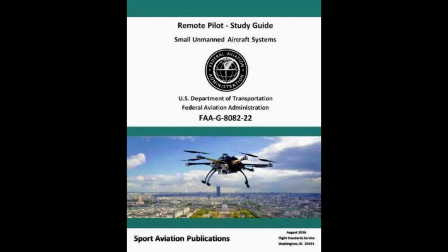2. Weight changes during flight also have a direct effect on aircraft performance. Fuel burn is the most common weight change that takes place during flight. As fuel is used, the aircraft becomes lighter and performance is improved, but this could have a negative effect on balance. In small UA operations, weight change during flight may occur when expendable items are used on board, e.g., a jettisonable load.